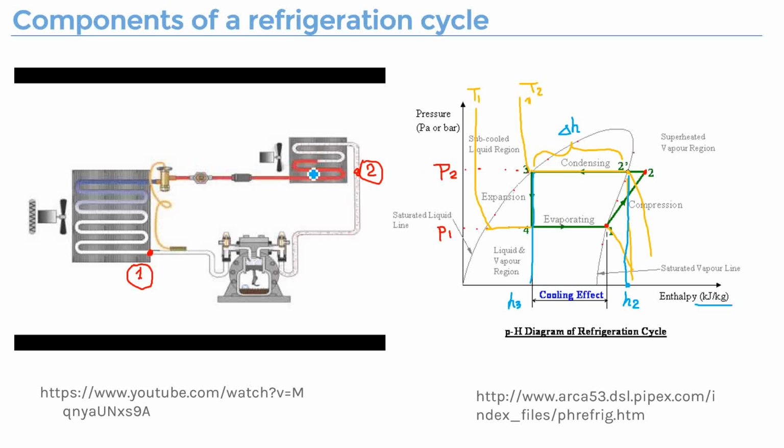So obviously, you could know the mass flow rate of the refrigerant, usually in kilograms per second, m dot, times delta H, which is kilojoules per kilogram. Then you will get this Q dot. M dot times delta H. And that gives you kilojoules per second, so that's kilowatts.